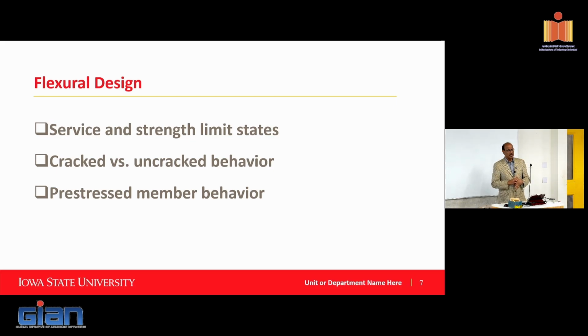One of the advantages of precast pre-stressed concrete is that if you have a floor slab for dead and live load, it's going to have some kind of deflection. You can apply pre-stressing and create an upward deflection. By the time the load comes in, it goes back to almost zero deflection. So that helps you to keep the floor slab crack-free, for example. It's not a difficult thing to do, but you don't want to crack the slab when you ship it or anything like that. So it has to be looked at.